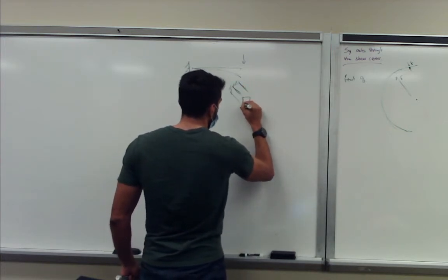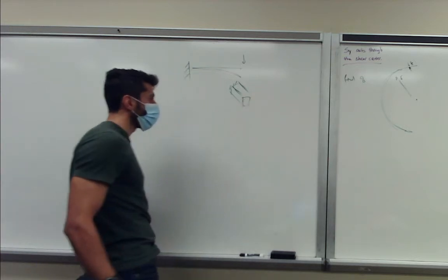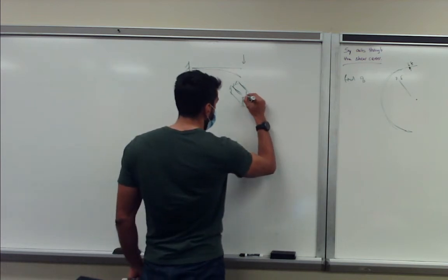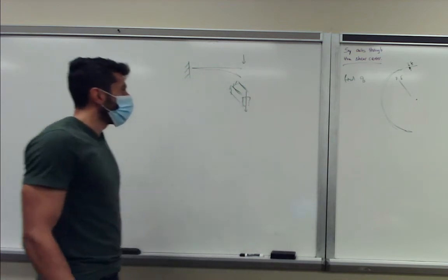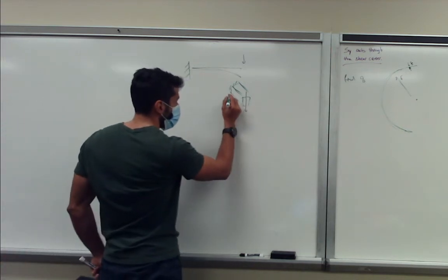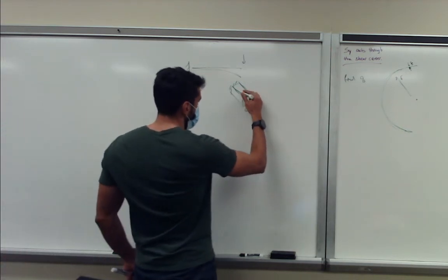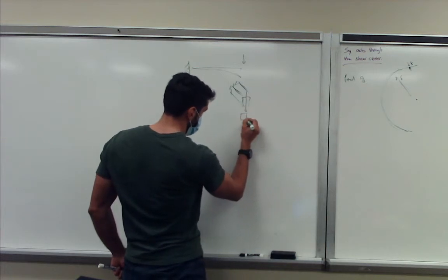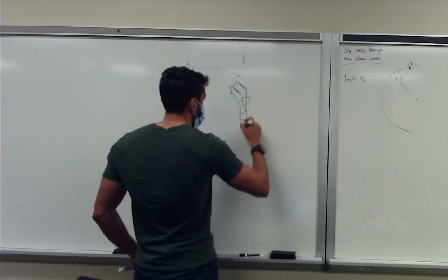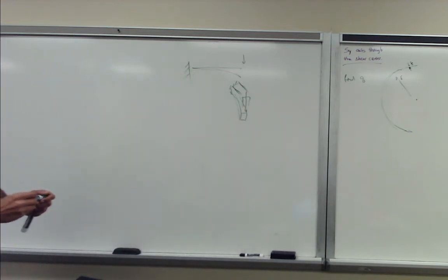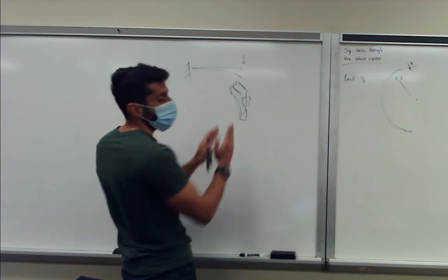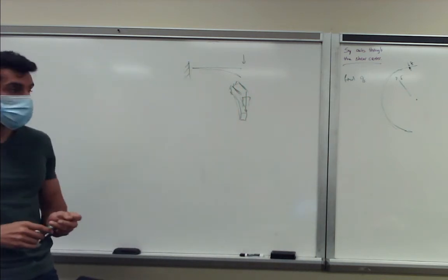Let's assume it's thin walled. If you now place the shear force in the middle, we get classical bending, right? Our structure bends in a linear fashion, and the plane of our square box cross-section remains plane. It just goes downwards in a linear fashion.